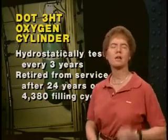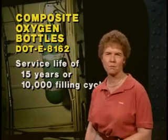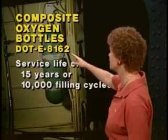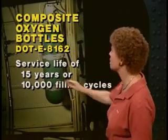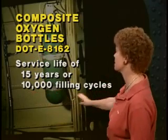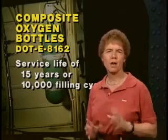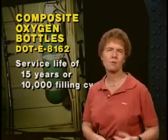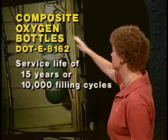On the other hand, a third type of oxygen bottle, a composite oxygen bottle that conforms to DOT E8162, has a service life of only 15 years, but it gets 10,000 filling cycles, whichever comes first. Now, the FAA will try to mix you up between the requirements for the lightweight 3HT cylinders and the composite oxygen bottles.